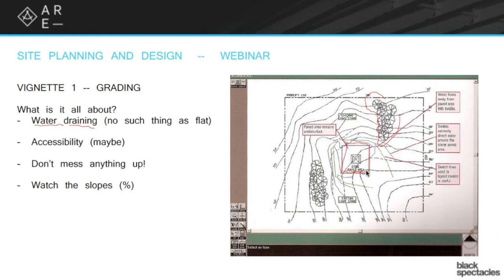When you use percent for a slope, let's say you're talking about a 20% slope. What that's referring to is every 100 feet horizontal is going to be 20 feet vertical. So if you start doing the math, that would mean that for every 1 foot vertical is 5 feet horizontal, right? So it's the same ratio. It's a way of thinking of it as a ratio.